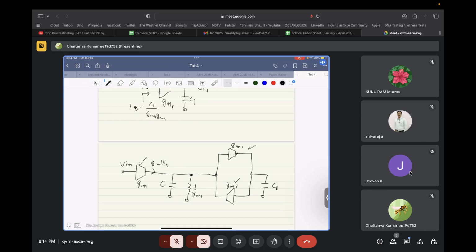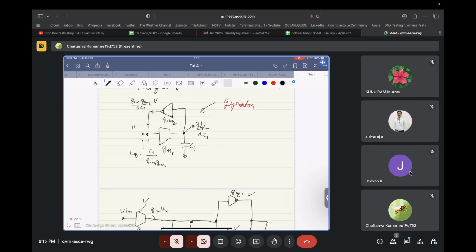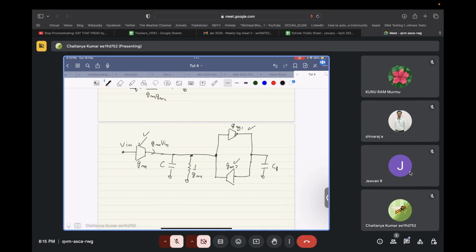Now one thing that I will comment on over here is since all of them are made through transconductors and capacitors, the values of these transconductances and resistance and capacitance are not always the same. Due to change in temperature, due to change in the operating voltage or mobility, something can change, and the values of these components can change.